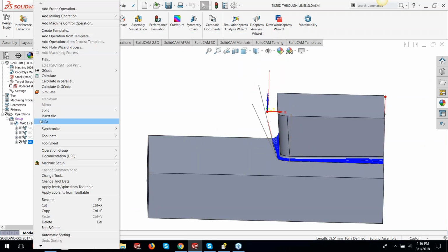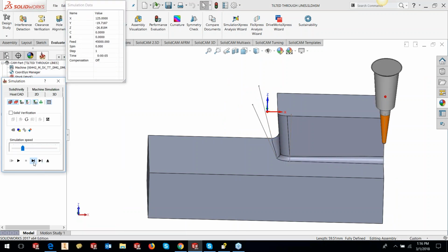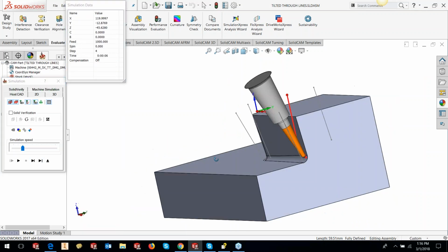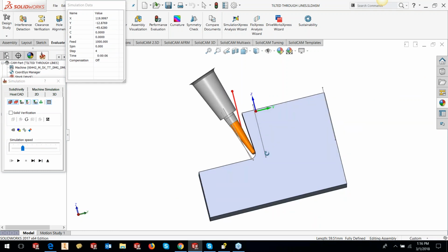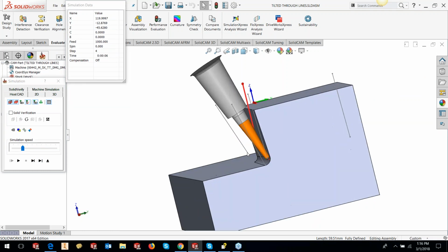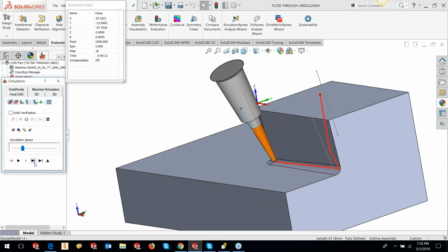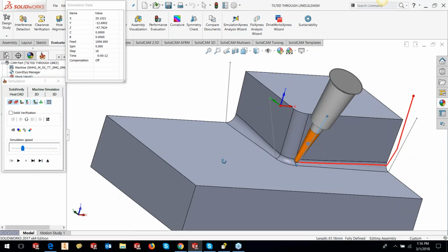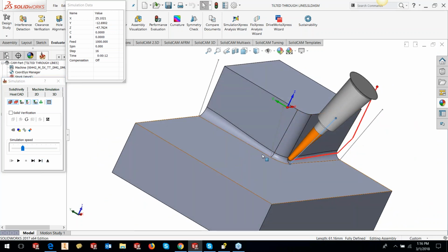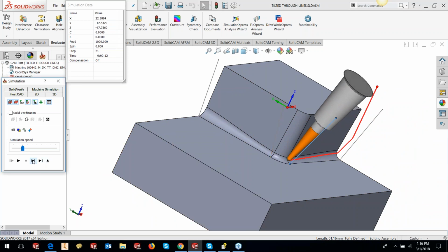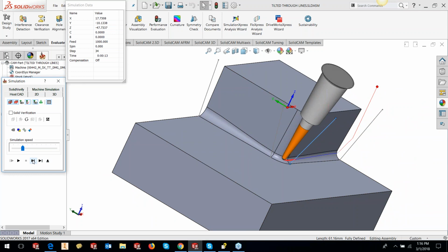So now what it is going to do is it's going to keep the tool orientation not with this line, but with this line, the second line here. So it's going to now come all the way from the starting point till this point here with the tool axis that is parallel to this line. Okay, you can see that it's parallel to that line, and from here it will now shift its tool axis and go parallel to the next line, because it finds the nearest 2 possible lines within the snap distance.